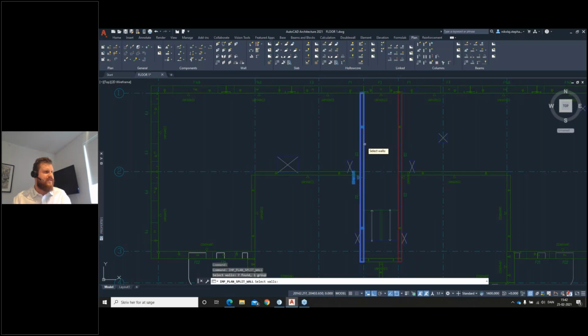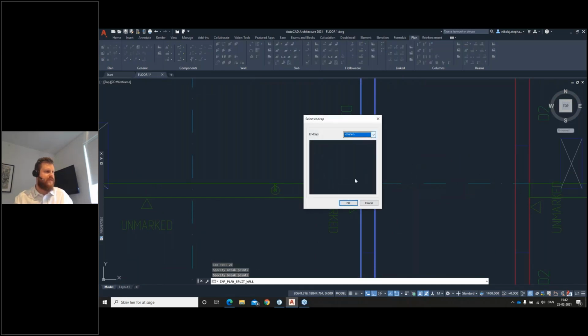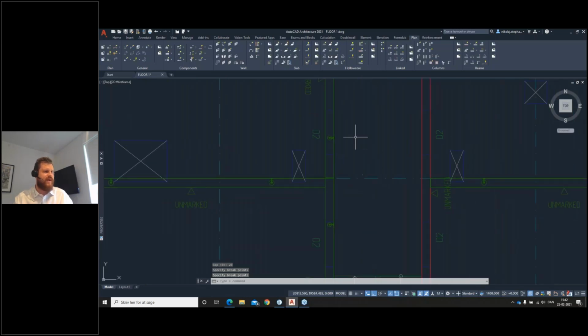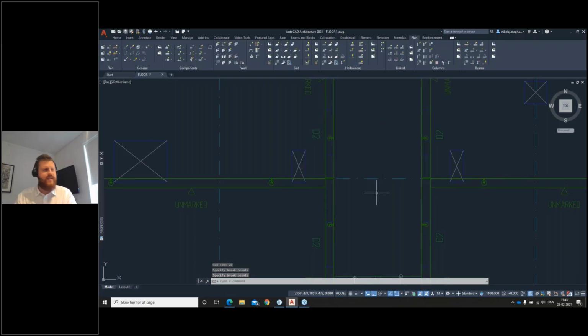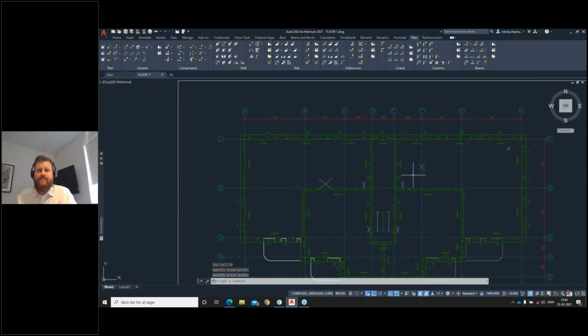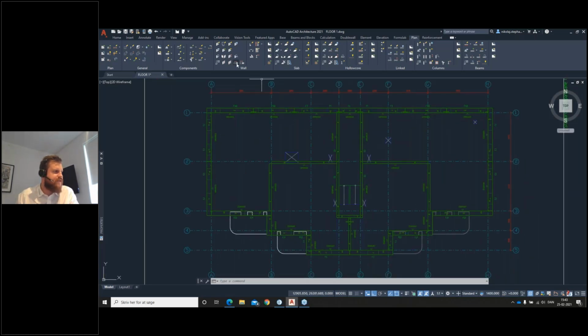So basically I can split using our regular split command here. Just saying, well, then split the wall panel here. Use a connection. I really don't have to do that right now. And the same thing, again, I want to do this wall here as well. So we're actually building our model now. But at the same time, now they're green, as you can see, at the same time as we're building our model, we're also building the shop drawings. And that's, of course, what I want to show you just in a couple minutes.